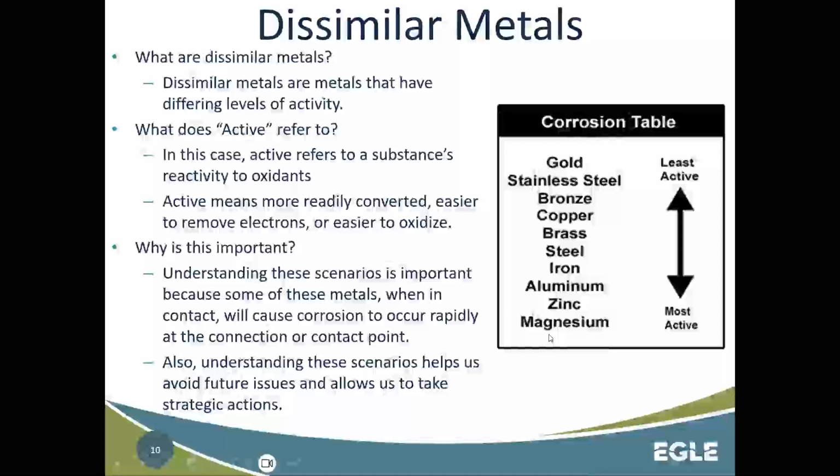You have your magnesium rods, your zinc rods, you might even have aluminum rods, anode rods that you put into a hot water tank to basically protect that iron or steel container, the actual tank itself, okay.